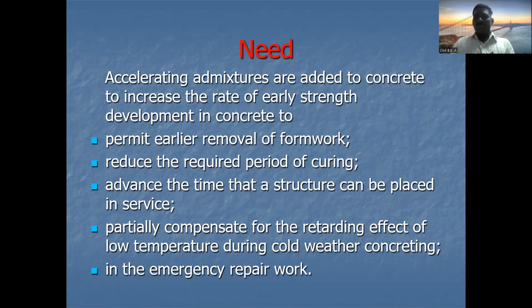As we are using cements of various grades in the concrete, the setting time of cement is not less than 30 minutes initial setting time, and not more than 600 minutes final setting time.